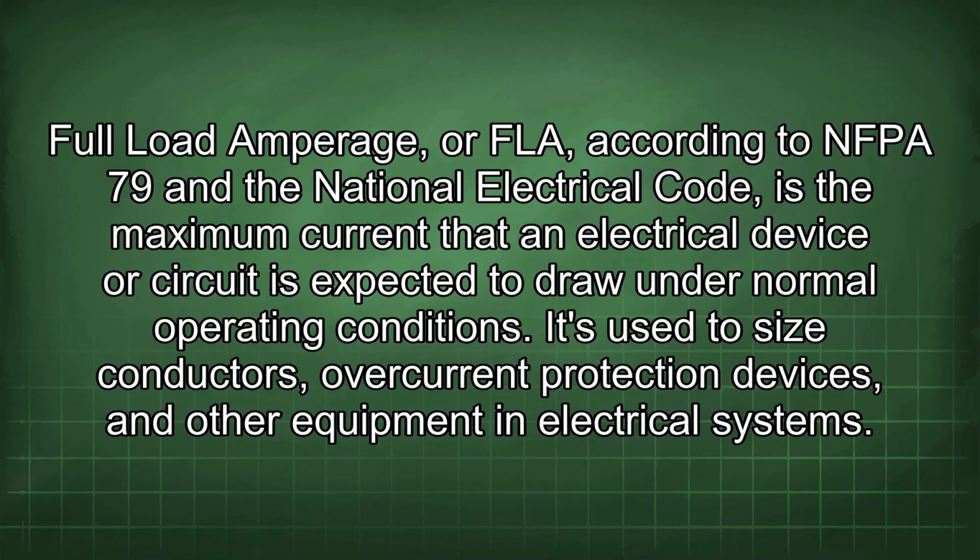Full load amperage, or FLA, according to NFPA 79 and the National Electrical Code, is the maximum current that an electrical device or circuit is expected to draw under normal operating conditions. It's used to size conductors, overcurrent protection devices, and other equipment in electrical systems.